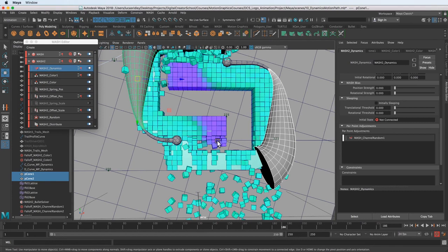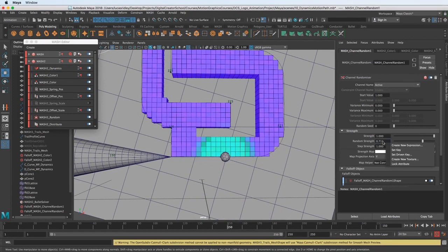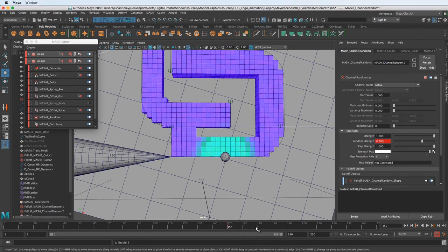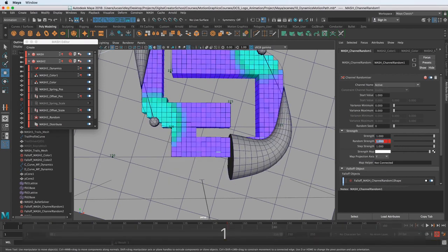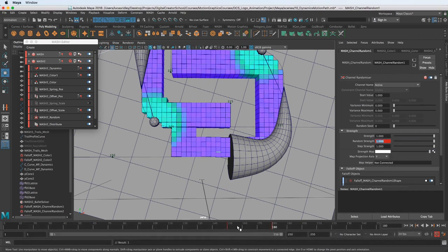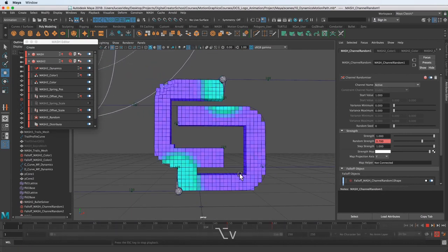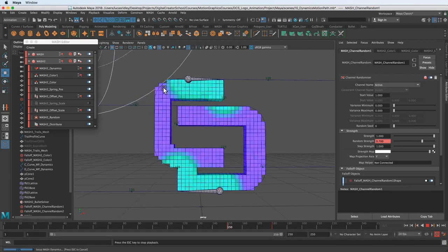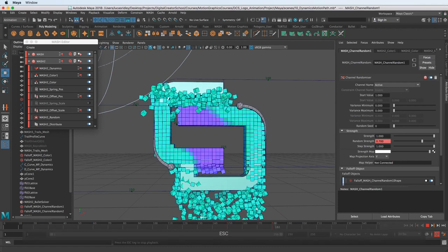It's all coming down. So I'm going to select dynamics to get to the per point adjustment that we made. And at 150, I'm going to have the random strength be, let's just have an even number of 0.7. I'm going to set a keyframe. I'm going to go maybe, let's see, 20, it's maybe 30 frames. And then I'm going to have this to be 1. And I'm going to set a key just to make sure. But we can see the 2 keyframes here, so that for sure did it. Set those keyframes. I'm going to play this back. Spring ends there, like we talked about in the other lesson. Randomization of that initiation. Now it all starts to really go as it gets closer to this 1 value.